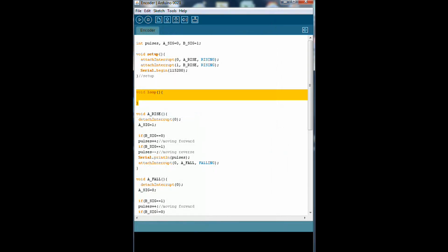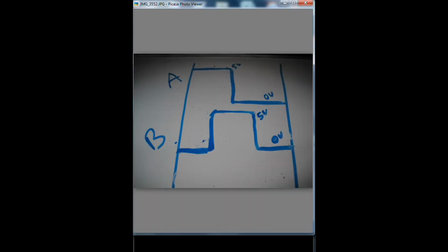So let's talk about this a little bit. We have the interrupts triggering the rising event of either the A signal or the B signal. Let's start at point 0 and walk through the code as if we're rotating through this. Right now we're at 0. Let's say the encoder is sitting at 0, 0, which would be somewhere out here, or basically right here, because this thing does repeat itself. So it would be right around here, 0, 0.